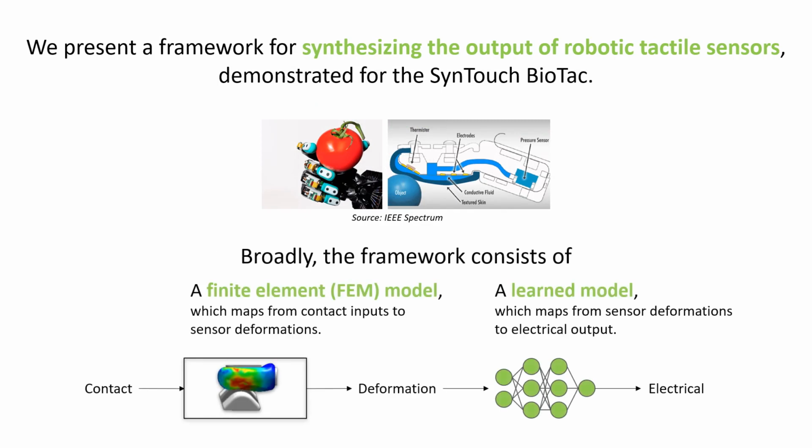sensor. The framework consists of, first, a 3D finite element model, which maps from contact inputs, such as forces applied by external objects, to the resulting deformations of the sensor. And second, a learned model, which maps from these deformations to the electrical output of the sensor.